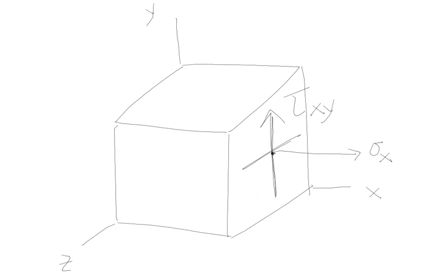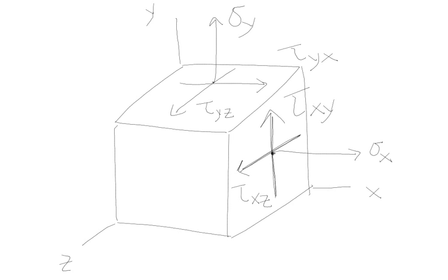This shear stress is what I'm going to call tau xz. It's on the x face in the z direction. Let's go to the top. This is sigma y. This is tau y face, because this top face is perpendicular to the y-axis. And then in the x direction, I'm going to have a shear stress going towards the z direction. That's my tau yz.